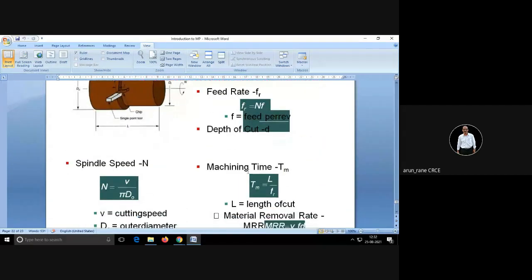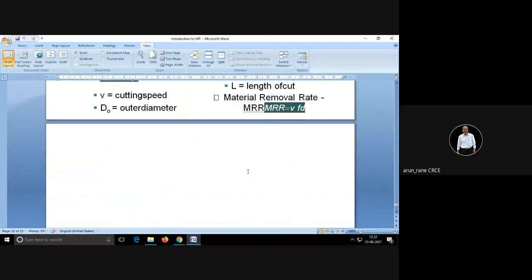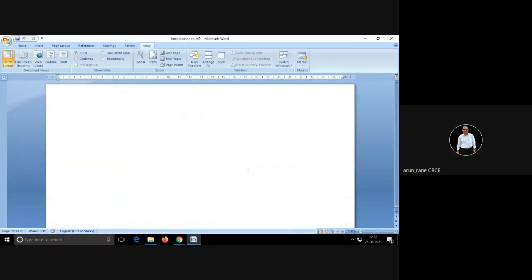Then now you know, now these are very simple, like suppose now Siddharth has calculated. Siddharth, the last question to you and we can pack up. Like suppose you have said now 20 millimeter per minute, correct? No, is the feed rate. Now, if I want to turn a length of 100 mm, how much time will it take?